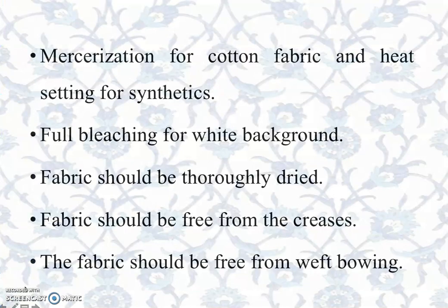Mercerization of cotton fabric and heat setting for synthetic fiber. Full bleaching is done for white background fabric. After the pre-treatment, the fabric should be thoroughly dried. The fabric should be free from creases. The fabric should be free from weft bowing.